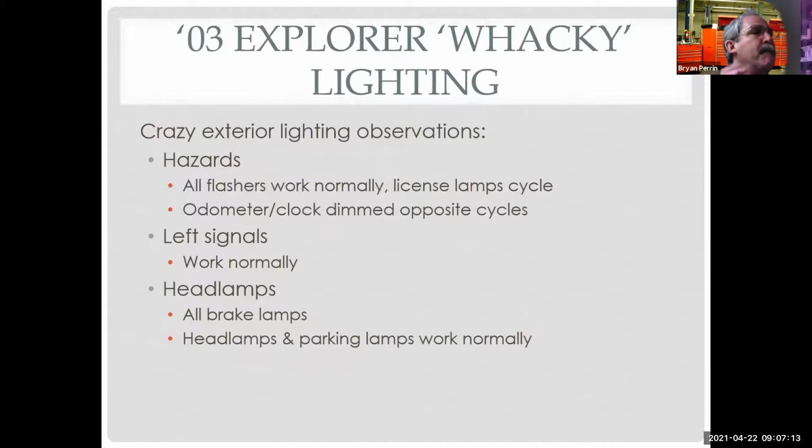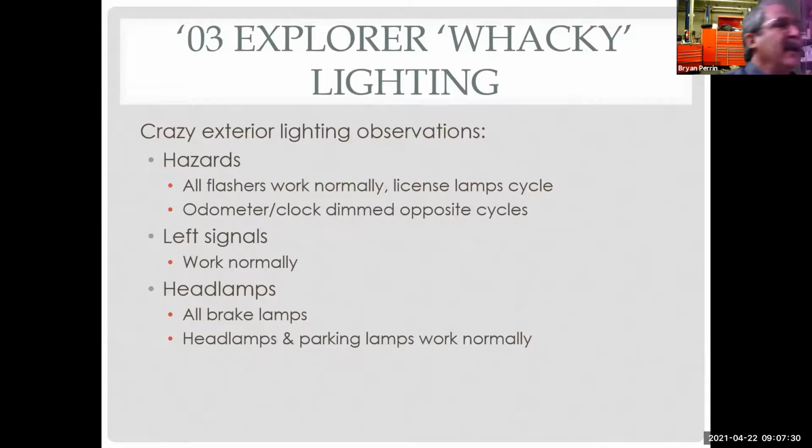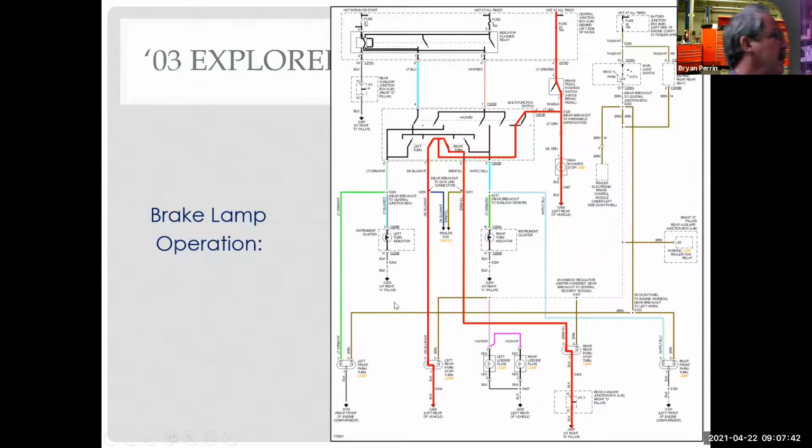And since multiple systems are being affected, by what we call parallel control, where I turn on this and this over here turns on, that is almost always a short to power. So if it's a short to power, I need to analyze this and figure out what can't be wrong and what could be wrong just by thought, and then compare the wiring schematic. So I'm going to take the wiring schematic for this vehicle, and I've highlighted in red each of the different operations.